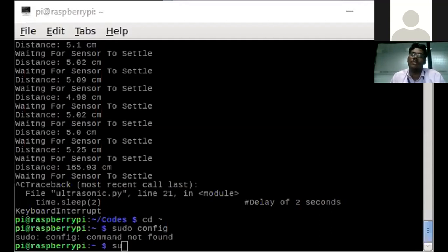After that, you unplug the SD card and plug it into the Raspberry Pi, connect the power supply and the HDMI port to a laptop, and just boot it. After booting it, use Advanced IP Scanner to find the IP. Based on the name, it shows Raspberry Pi at mshome.net. It is the default name for any Raspberry Pi. If you didn't change it, it will be the same. If you change the name, it will be the name you have given. The name and also the login ID and password can be changed. I can show you how to change it.